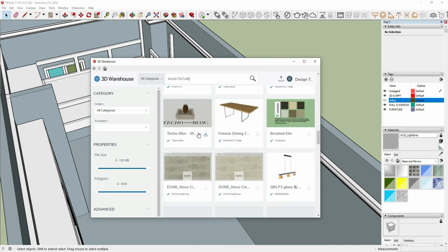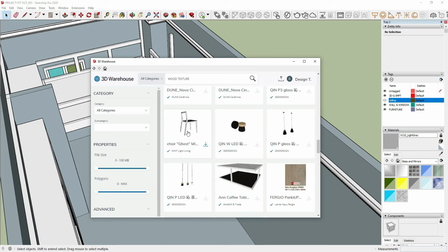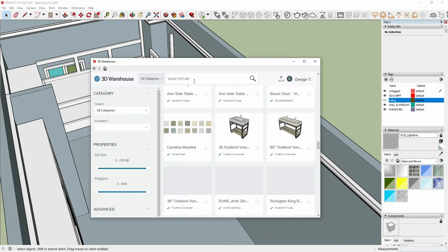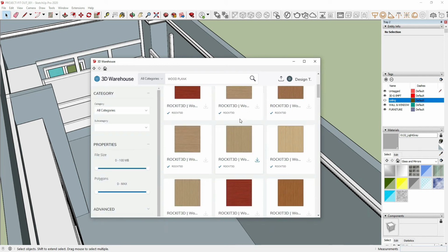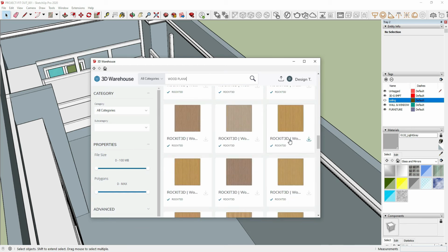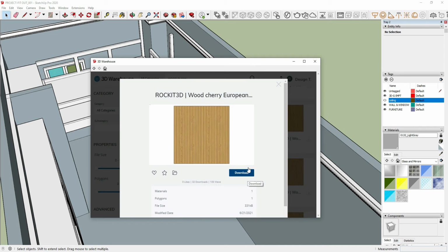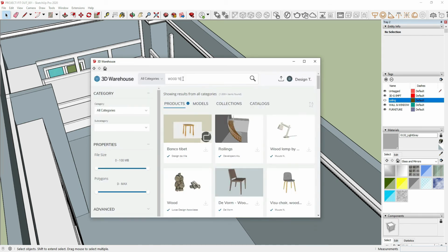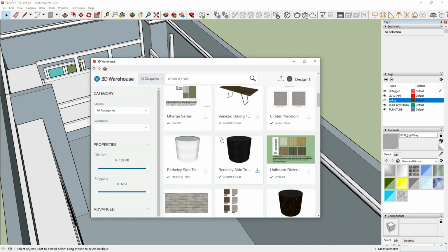First, I used the 3D Warehouse and found the texture that suits our project. In addition, I made trial and error in finding the best texture for our model. I collect all the textures from the 3D Warehouse models, use the Match Properties tool and apply it in our project model. The best selection is the nearest, if possible, to your project requirements.